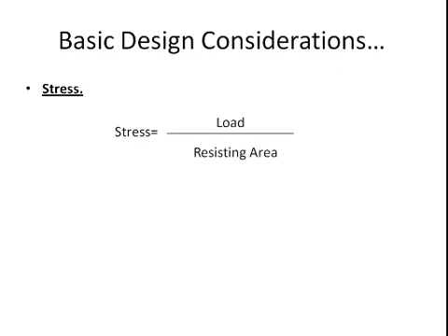Most of us have a misunderstanding that the stress acts only on the cross-sectional area. It is not always true that stress acts only on the cross-sectional area, but it acts on such an area which resists the externally applied load. It may be a contact area, it may be a cross-sectional area.